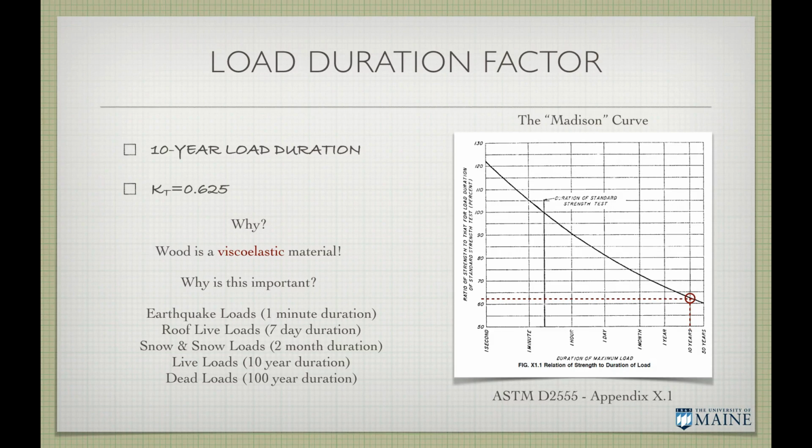But there are cases where we have, well, here, live loads that is our base, our 10-year duration. A live load is a term we use for designing a building, the people that come in it. So like a home is going to be designed for a 40 pounds per square foot live load. Over the life of the structure, it's kind of interesting.